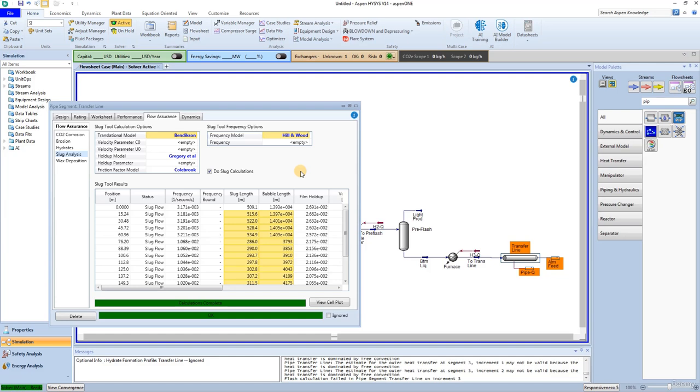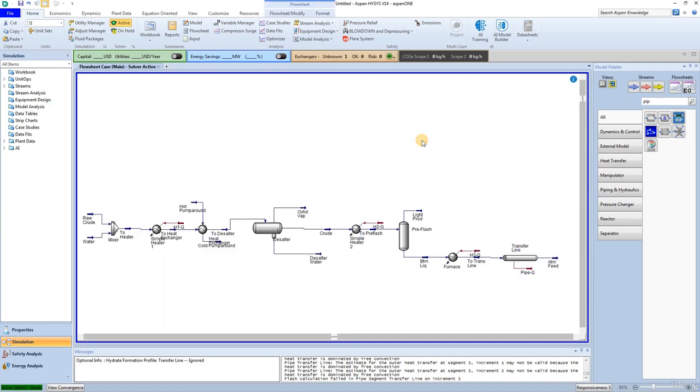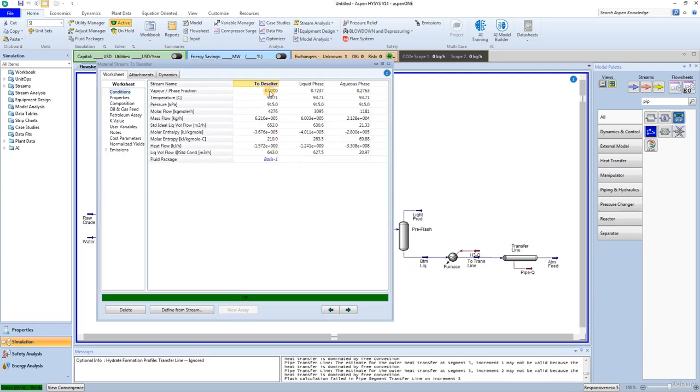Now to our third task, install, balance, and adjust blocks. Look at the vapor fraction for stream 2 desalter. It should be equal to 0. The feed to the desalter has to be liquid, but it could begin to vaporize given changes in the pressure at the desalter separator. Keeping track of the bubble point temperature of the 2 desalter stream would be extremely helpful.